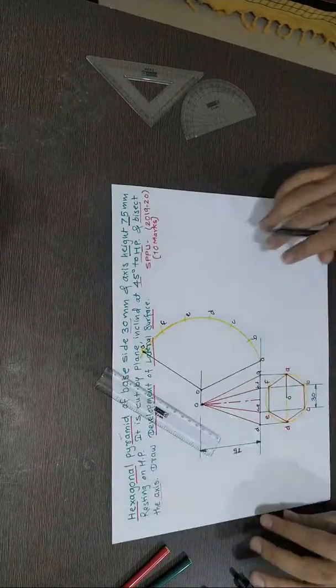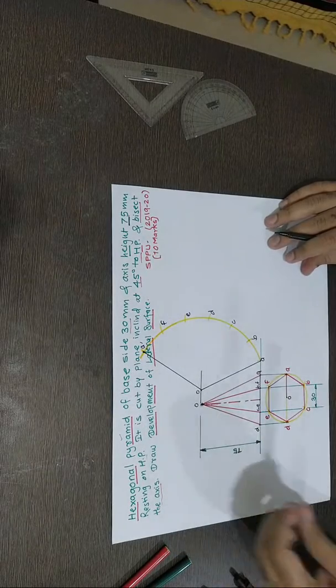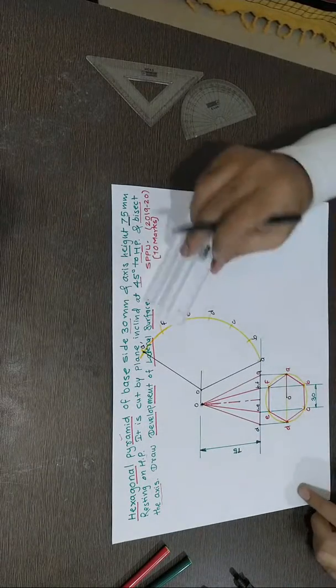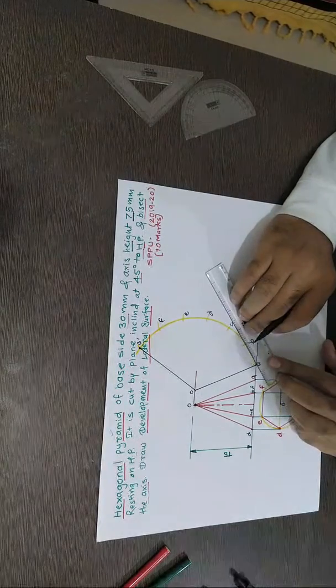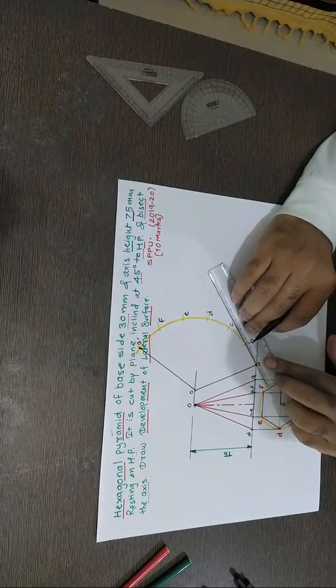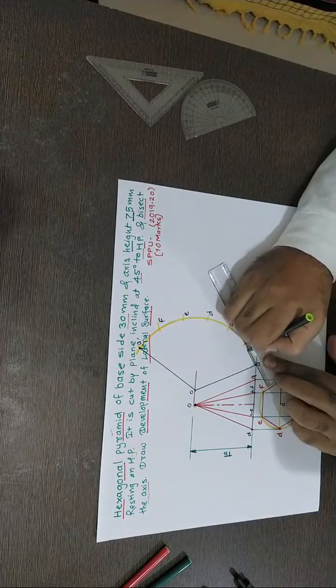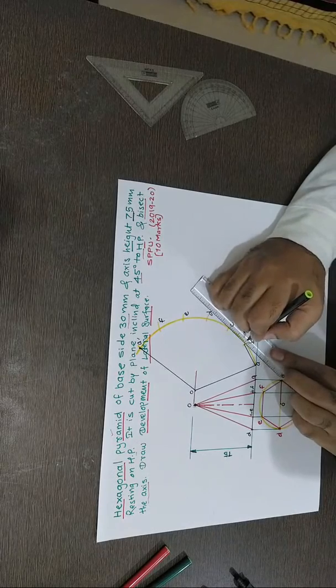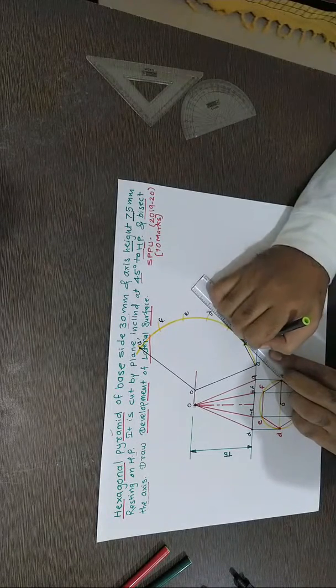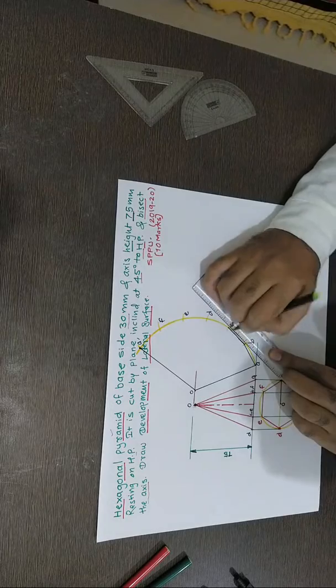Yes, so this is the development, what you can see. But it is not a cone to have a circular development. It is a pyramid, so it has edges for the base. With this assumption, we join all those ends with a straight line. So join AB, BC, and so on. So this is the actual approximation that we assume.